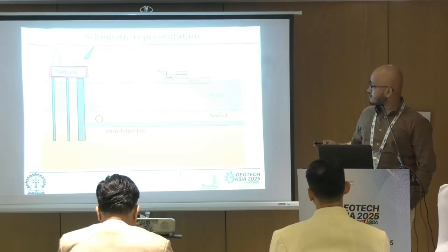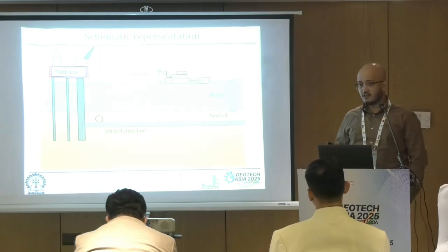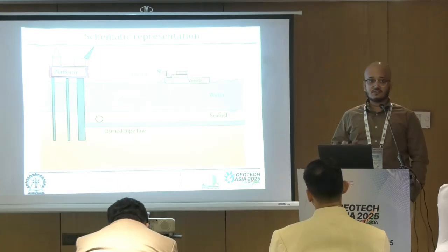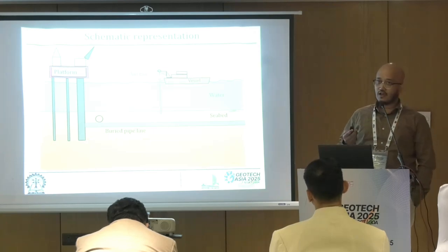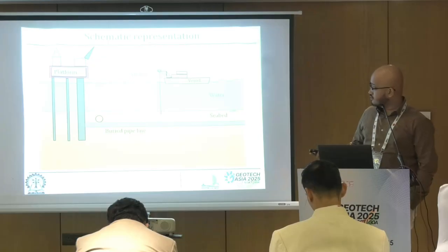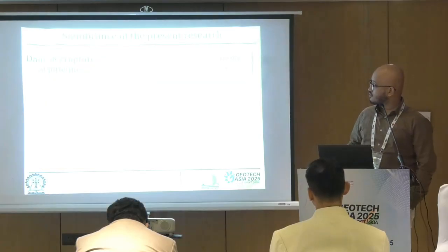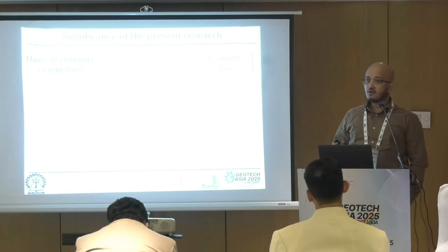A similar scenario is a vessel. If the pipe network is within the anchorage zone of ships, even in that case an anchor can drop in an accident, hit the pipelines, and cause damage there. Now these kinds of impact loads can cause damage and rupture of pipelines, which is an environmental hazard